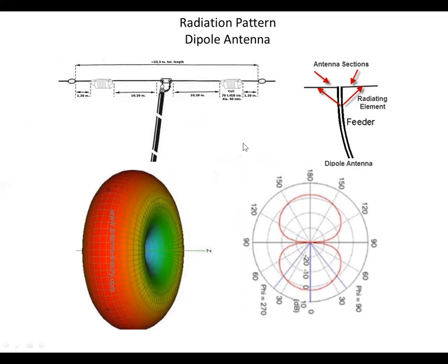When you make a comparison between antennas, make sure that they're using the same reference. And if they aren't, if one's dBi and one's dBd, then there's an addition or subtraction you make to get them on the same field.